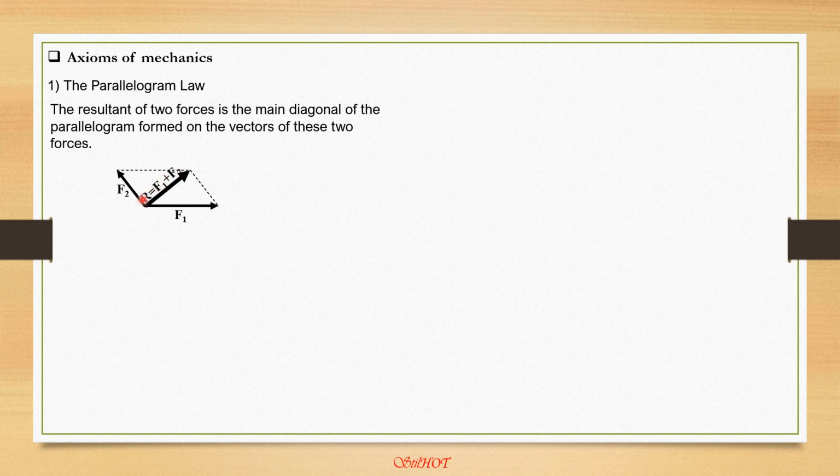This is to be computed geometrically by means of this parallelogram or by means of this triangle. Then for the triangle, you have to draw the first force, then connect the second force. The order of the arrangement of forces is irrelevant. So meaning to say, it is in any order.